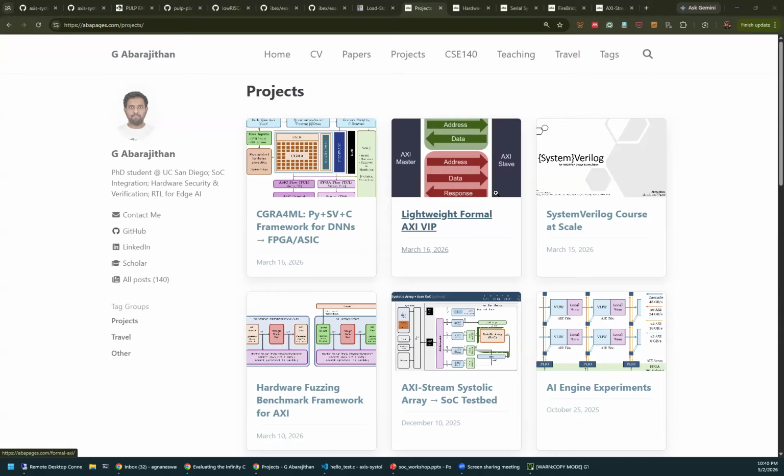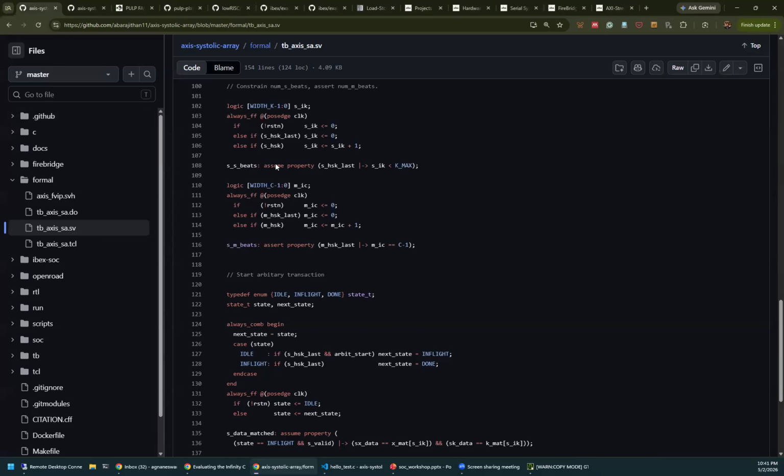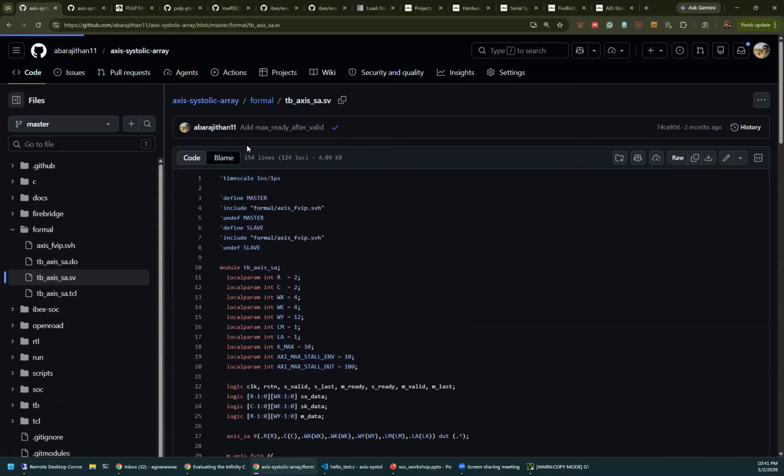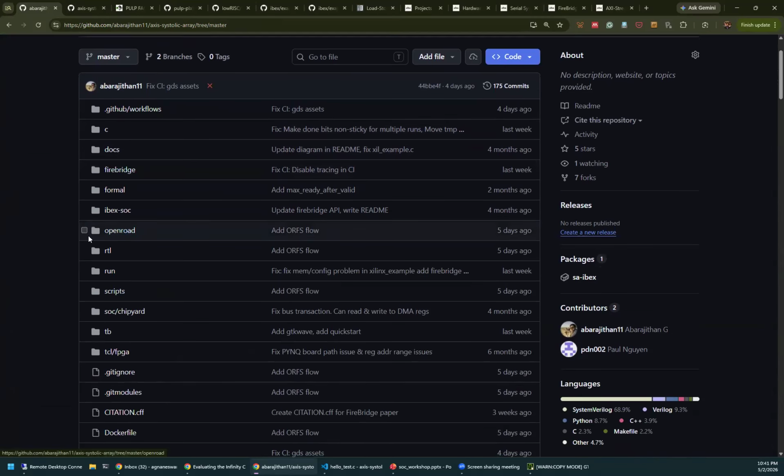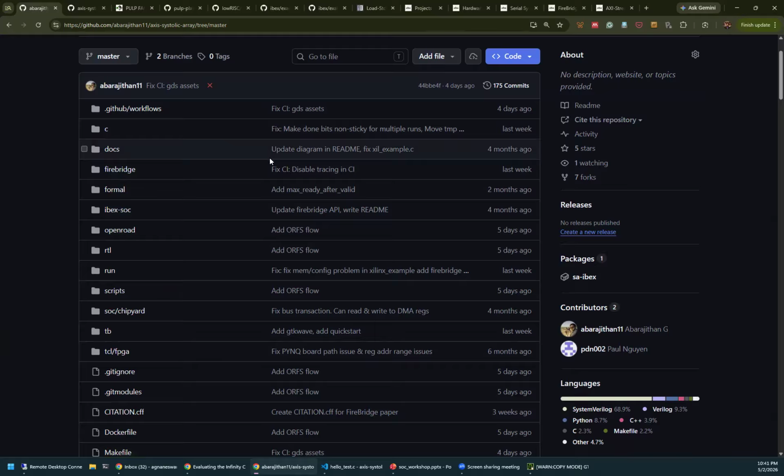One more interesting thing you can do: if you have an AI accelerator, you can interface it to Linux. I haven't done that part yet. I have a few undergrads working on that, and probably in a few months we will have it ready. Now we have the C firmware which runs on bare metal. Bare metal means it runs on this Zynq FPGA raw, without any operating system.